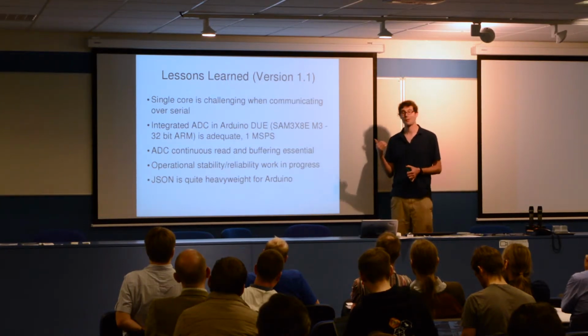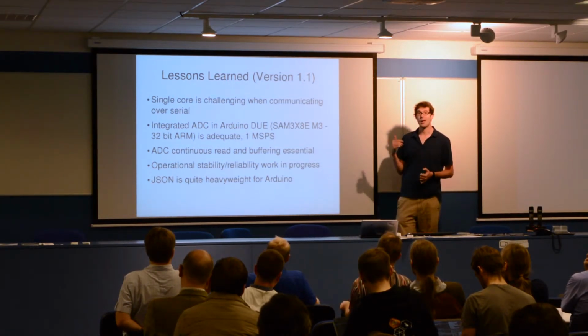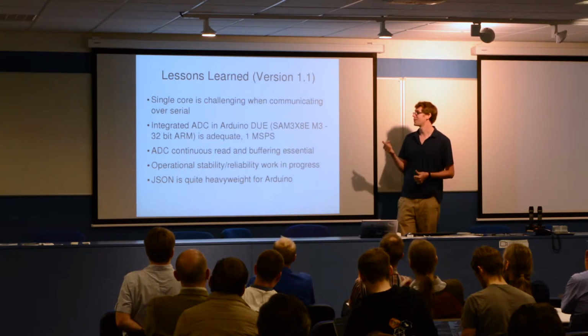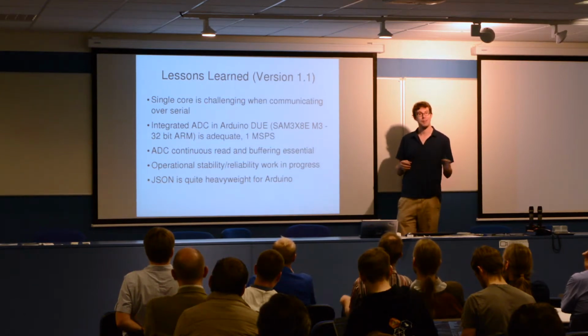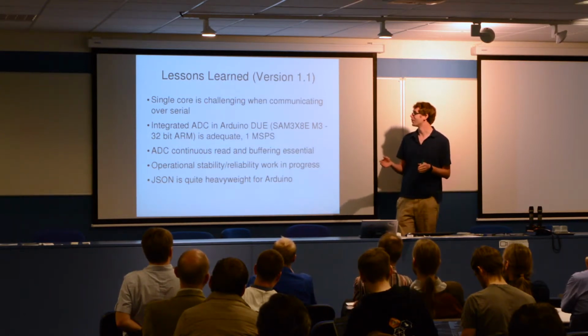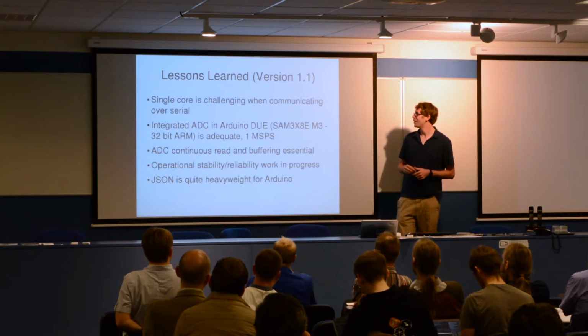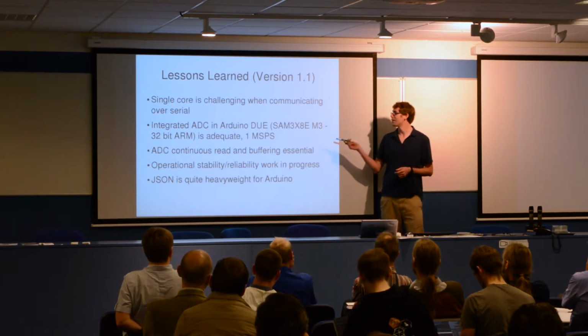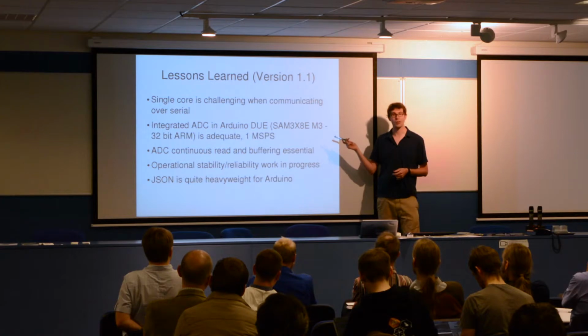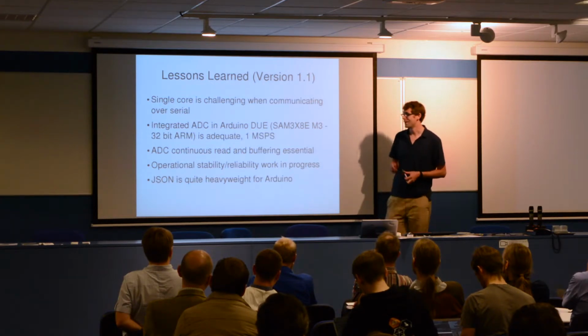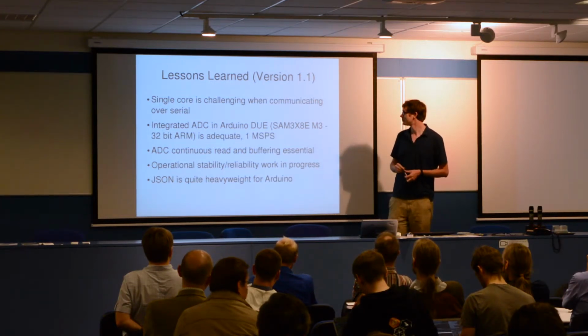Things we were working on from version 1.1: we're having difficulty using a single core architecture to actually read in the events that happen randomly and split them out over serial without having it crash. We found the ADC, we did some testing. The one that's actually built into the Arduino DUE is perfect for what we need.